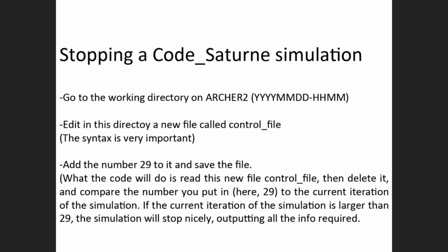One thing that you should take into account as well is that control file has a lot of other uses. You can look at the documentation. You can change many things on the fly while the code is running. So you can change, for example, how often you write a checkpoint, or how often you write post-processing, or how often you do many other things, as well as forcing them to be written at a given time step. So if you want to know more, you can find that in the user guide.